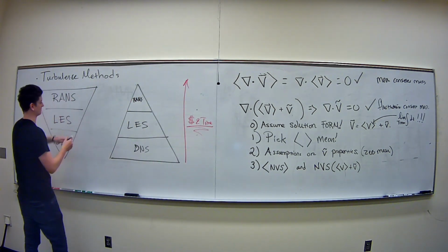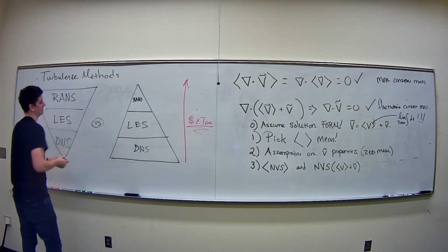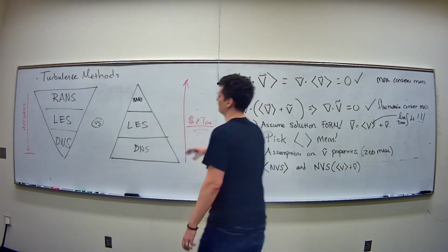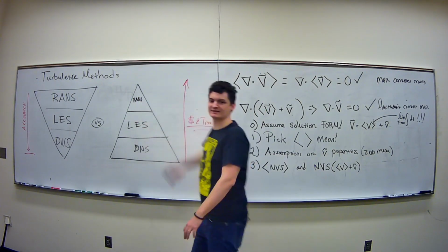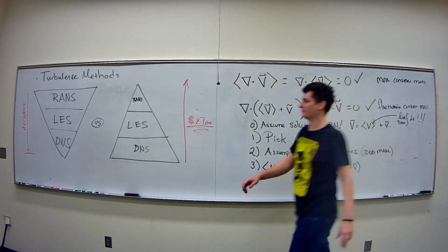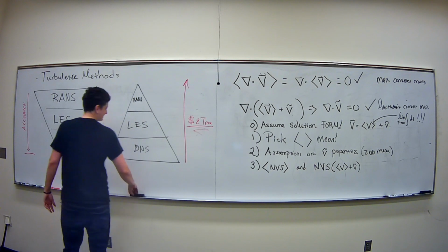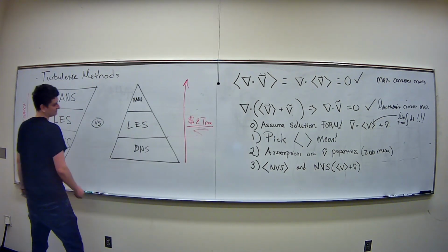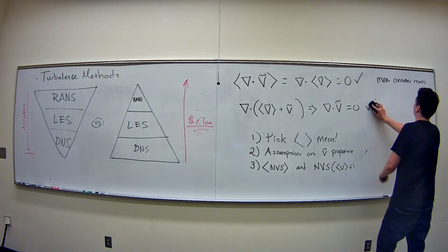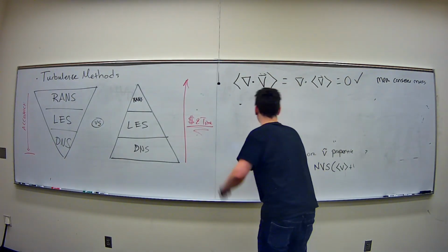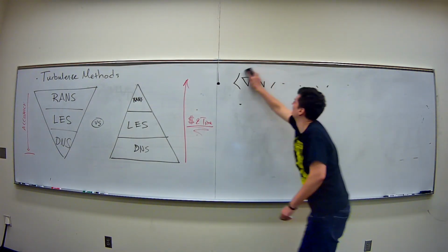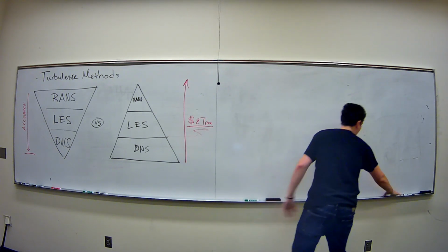And these are corresponding, right? So it seems like a good bet is this LES simulation. I won't go over LES, but I want you to appreciate that RANS is this idea of here's my average, a time average to infinity with nothing else. LES has a very fancy average it chooses. What the LES does is it picks a super fancy average. The large eddy simulation is an assumption on the average.